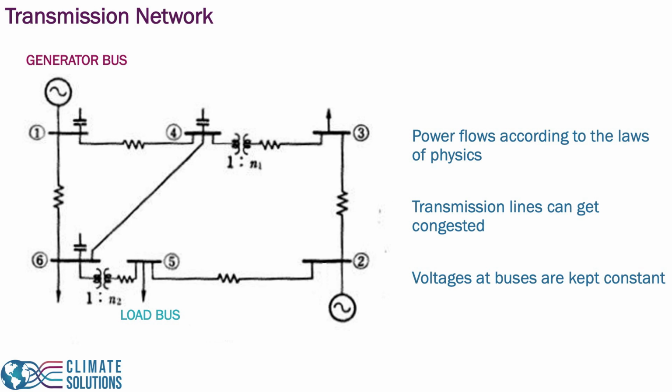When a line sags, it can become too close to the ground to be safe. This means that we have a limited amount of current that we can transmit through every transmission line. That establishes a power capacity limit. When the power hits this maximum limit of the line, we say the transmission line is congested. And you can see right there the congestion is, for example, indicated here on this line in red.